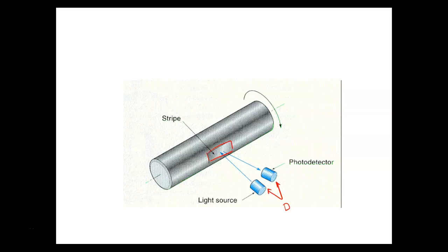So it starts with a D. We know it's a photoelectric sensor. We only got three: we got a through-beam, diffused. Yeah, this is a diffuse sensor. So what it's actually doing, it's going to come over here, but we're controlling the view by putting a little cellophane, usually like aluminum foil or something that we consider highly reflective. So every time this highly reflective piece comes back around, it will bounce the light back, and of course that only gives us pulses, right? You understand? And then we would have to somehow convert that over to a speed.